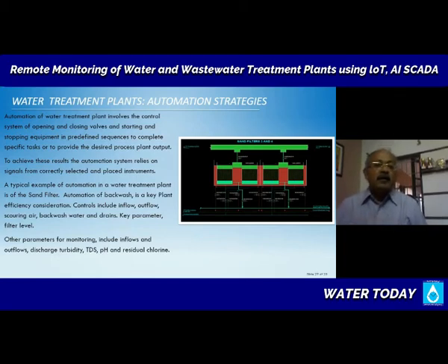That is one part in a water treatment plant where the efficiency can come. Now, other parameters, of course, when you are sending treated water out to customers, you have to monitor certain parameters. So what is the inflow and what is the outflow from the plant, for example? And then depending on the treatment process, you have other measurements. But largely, look at the water quality that is going out. What is the turbidity of the water in nephelometric turbidity units? In other words, how clear is the water after your treatment?